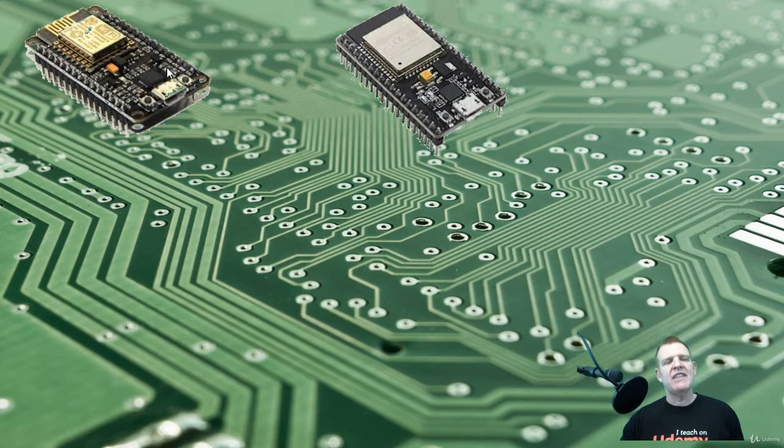I will say that whichever one you buy on the ESP8266, you probably want one that's breadboardable. And what I've noticed is you want to get the 12E model because it has these pin rows out here. And also you want to make sure that it has 2 free rows on your breadboard. I know the very cheapest ESP8266s take up 7 out of the 8 rows of the breadboard. So just make sure if you're going to breadboard it, you get a free row on each side. The ESP32 Dev Kit C, it's the in-house made version using this chip.